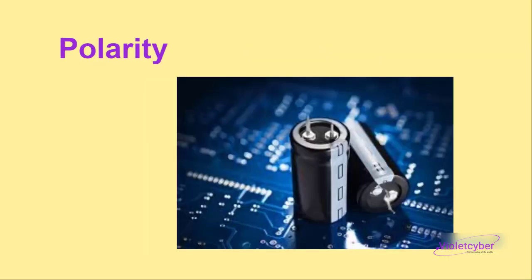Polarity. Electrolytic and tantalum capacitors are polarized. Be sure to connect their positive and negative terminals correctly, as reverse connection can lead to failure or even explosion. Non-polarized capacitors such as ceramic, film, and mica can be used in either direction.